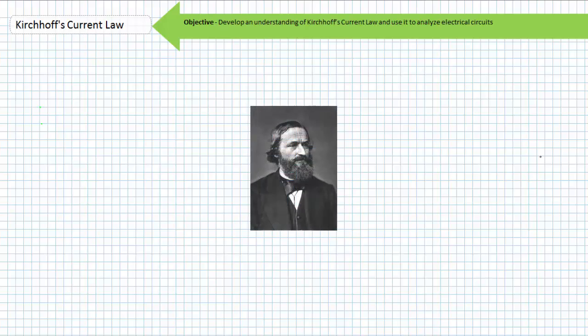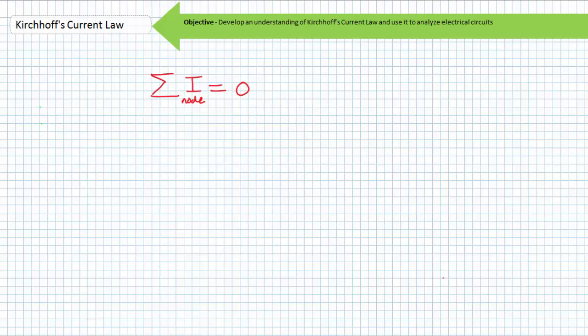The German scientist Gustav Kirchhoff in the mid-1800s was the first to apply such a concept to electrical circuits. The simple statement of what goes in must come out is reworded in Kirchhoff's memorable observation that the algebraic summation of the currents entering and leaving a junction of a network is 0. It may help to rephrase this ever so slightly and state that for any given node, the sum of currents entering the node equals the sum of currents leaving the node. One side is reserved for incoming current, the other side reserved for outgoing current. What goes in must come out.